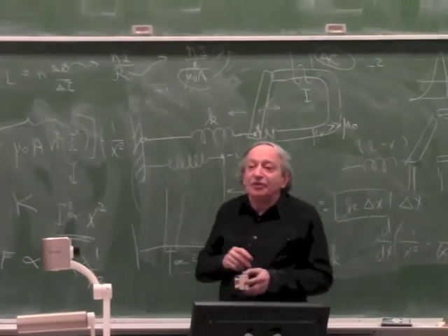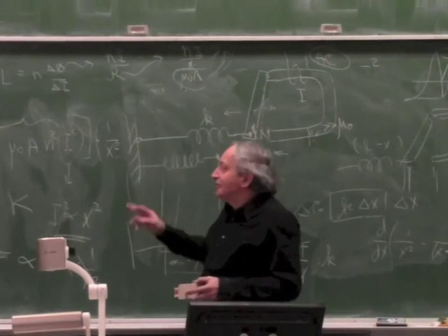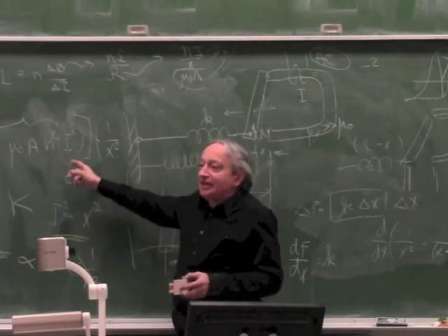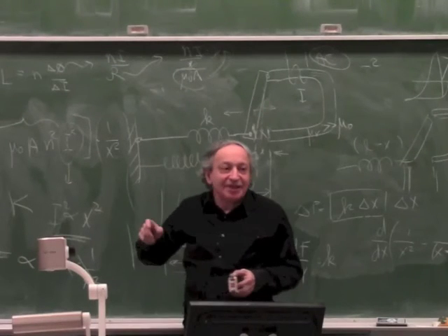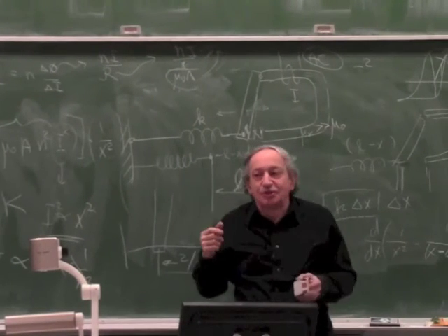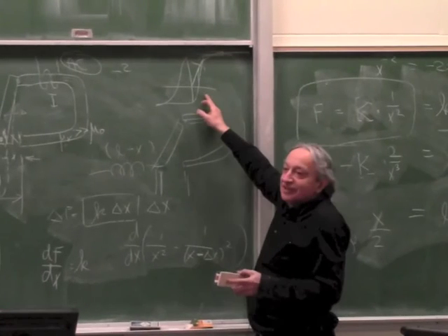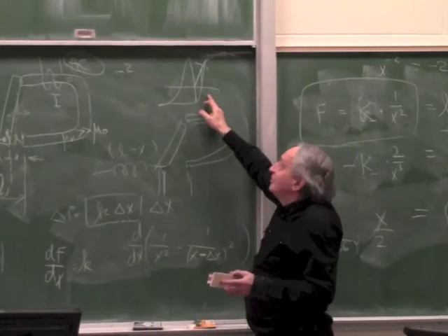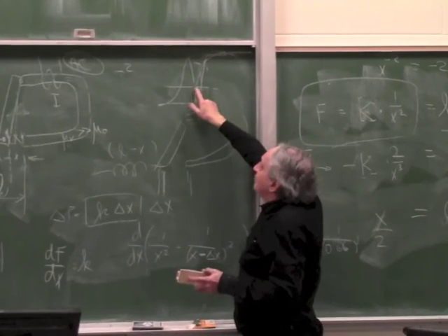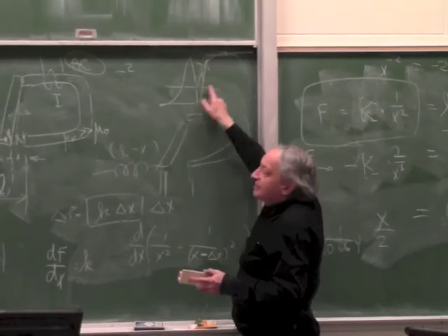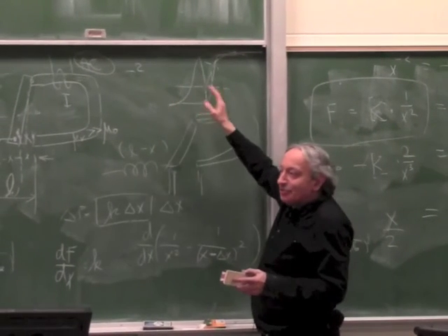Now, if you have computers, you can force it to linearize by measuring x and changing the I with the computer. But again, for that you have to model the saturation. The software which does that has to know this curve, and this gets very complicated because this curve depends where you're coming from. As you recall, if you came from here or from here, you get different hysteresis loops. So it gets more and more complicated.